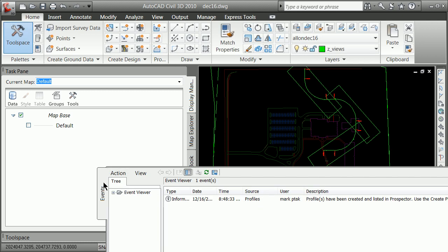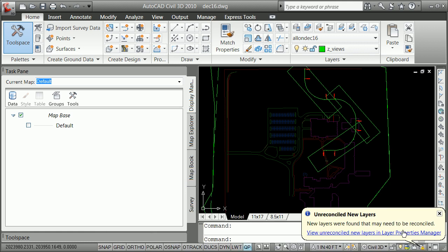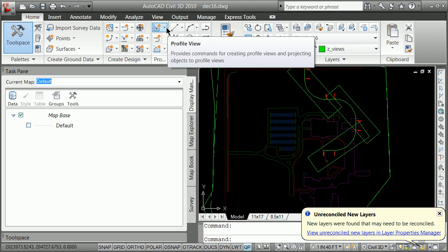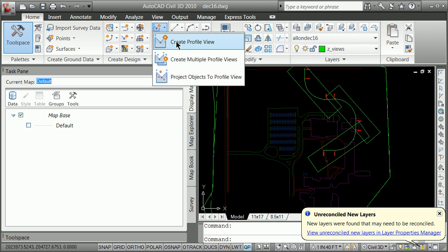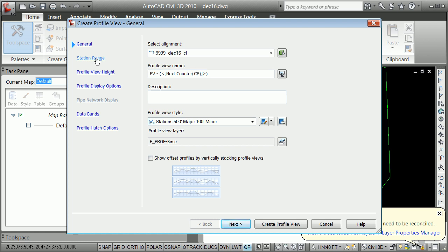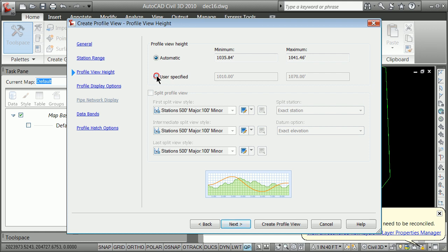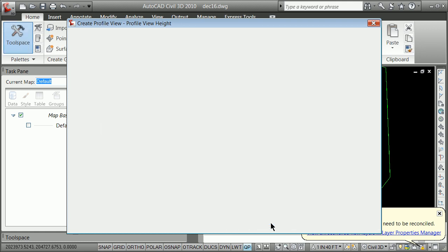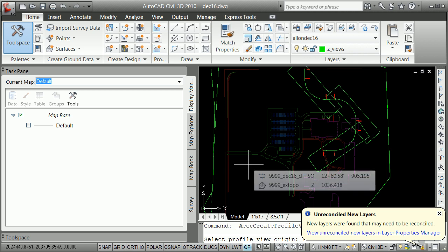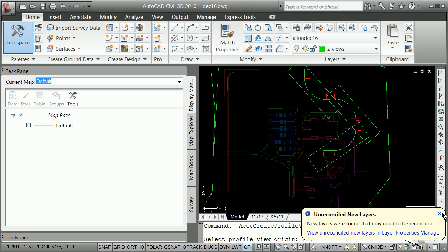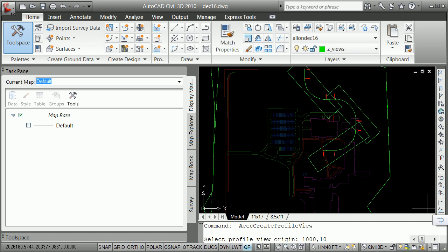It's going to give you an error here that says you've got the profile, but it's not stored in a profile view. We're at 941. The last step, you were getting at 1000, is you can go ahead and create a profile view. You're proactive about 1000, and proactive about the height, 1010. You're going to change this later. You're going to create a profile view at 1000, comma, 1010, 0. Zoom center 1000, comma, 1010, 0.